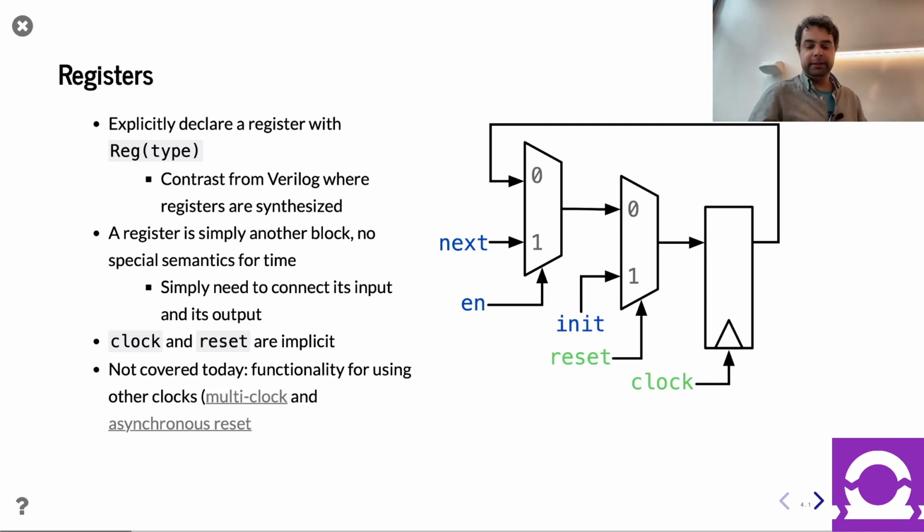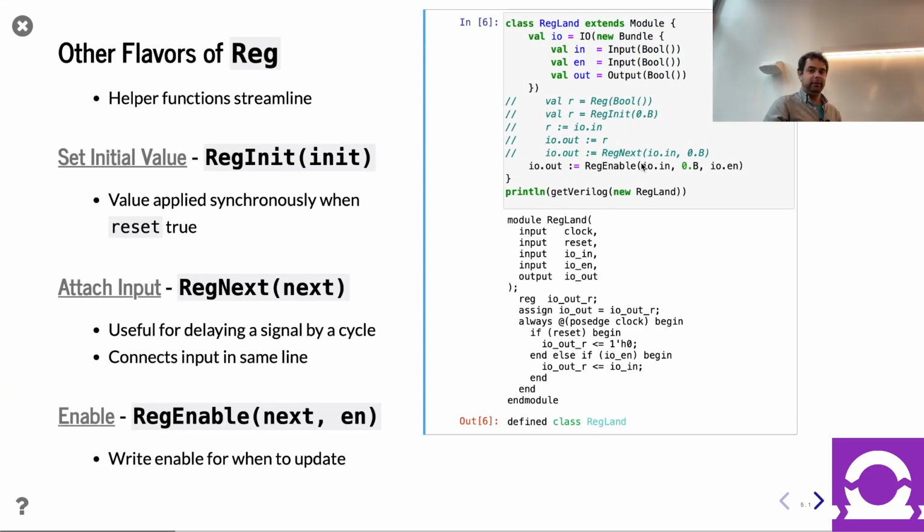For the most part, when you write Chisel code, especially in this course, as you see, we don't see us talking about clock. The reason is that these are all in the same clock domain. The clock signal comes in through this module automatically. It's connected. So there is a clock. It's just we don't need to see it because it's the same most of the time. It's only if you have different clock domains that you actually have to worry about seeing it. Cool. Other questions?